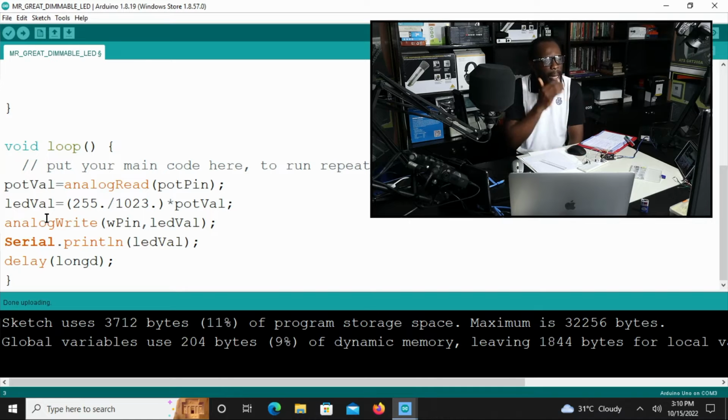So it's not a static number. The LED value flows from 0 to what? On the Arduino scale, the value is from 0 to 255. In real-world voltage, it becomes 0 to 5 volts. That is for analog write. And for analog read, you have 0 to 1023.